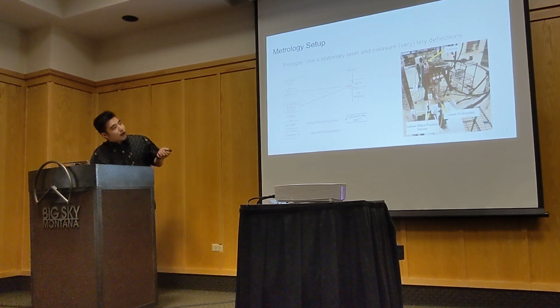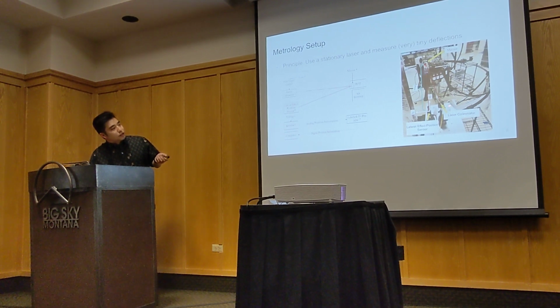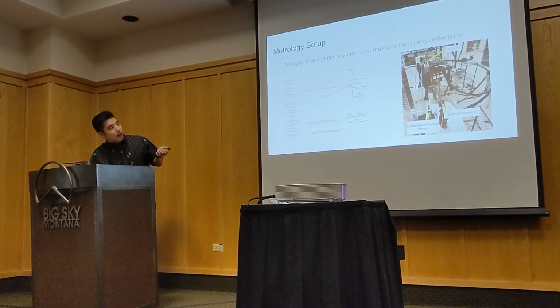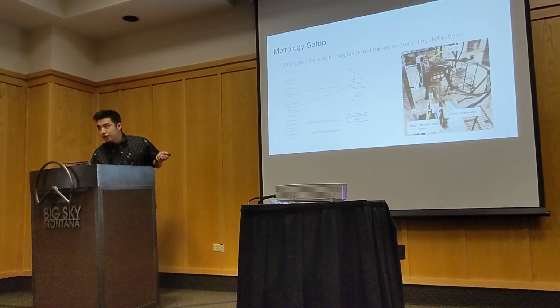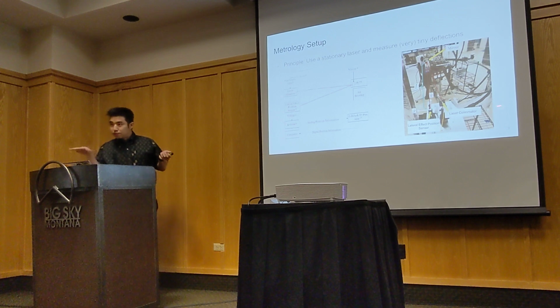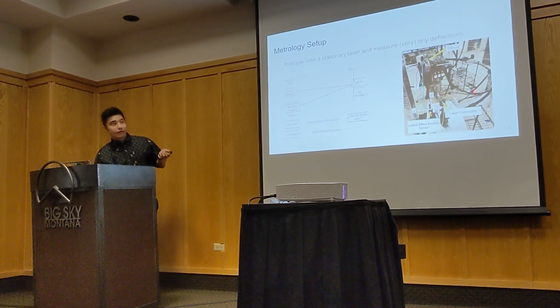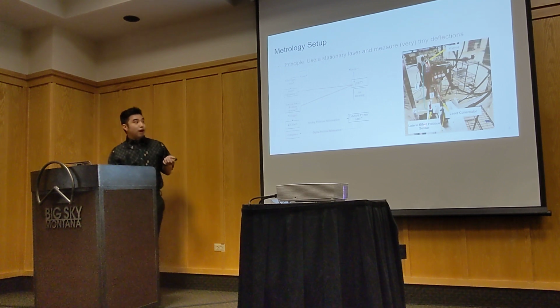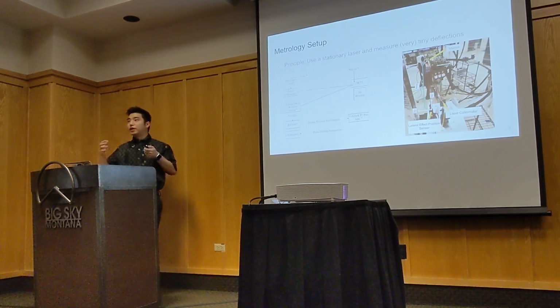On the right, I have a graphic of this metrology system integrated into the HSFL's ADCS testbed facility. HyTI is sitting on its 6U side on the support jig there. The mirror is placed there, then the laser collimator. I traced the path of the incident beam, and I've indicated the directions at which the lateral effect position sensor records data. The X direction data runs parallel to the ground, and the Y direction data runs perpendicular to the ground. I've indicated the throw distance L because we're going to divide these displacements by L to obtain an angular displacement.